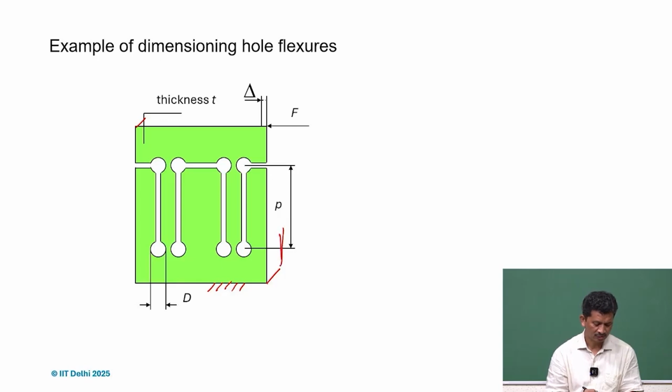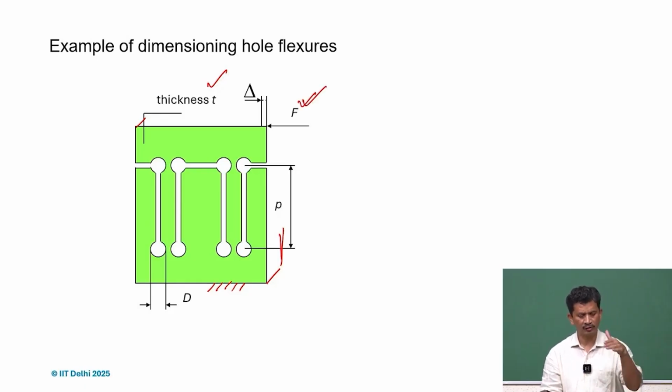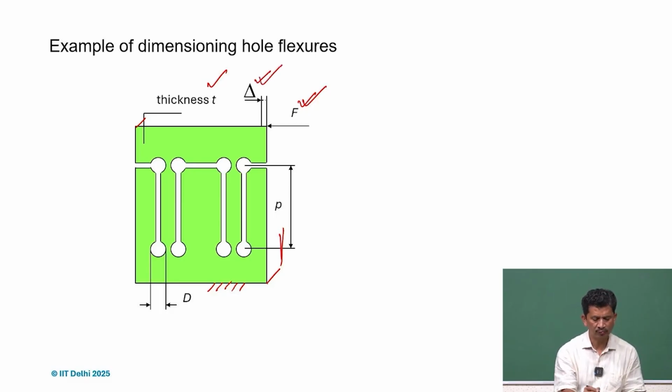So this is the T what we have, and yes, we drill the hole and then connect it, and we can get, out of wire EDM, this kind of features. So what happens if we apply force F, and we fix the bottom part, and the top part, if we apply any kind of actuation? So this will be the excursion movement, that delta, it can move.